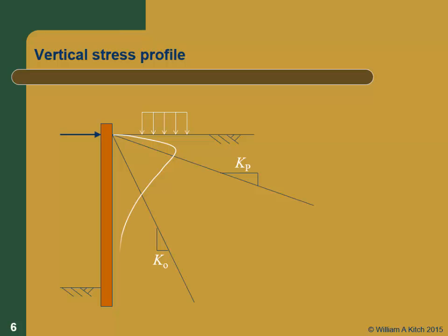So if this was my roller load and I just applied it at the surface, this might be my Boussinesq stress distribution that I would get. Right? Just from the equations we just went through. I've got a line load perpendicular to the wall, finite width line load perpendicular to the wall. I can go through that equation. I can calculate the vertical stress as a function of depth, and this is the figure I'm going to get.